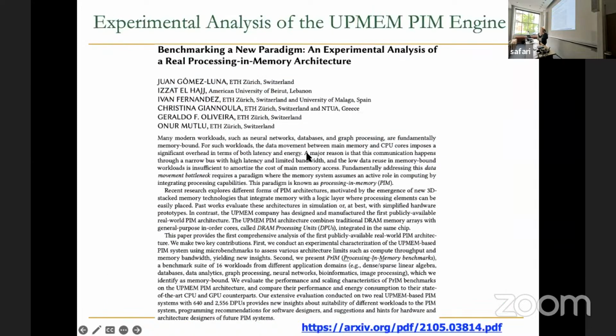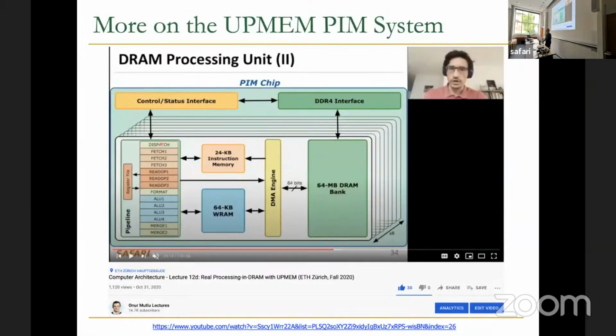There's some shared bus, as we discussed last time, but they're not doing it that way. They're not using that shared bus, unfortunately. They're doing computation, and they needed to modify some mechanisms, but they were not able to touch that part, the DRAM core, if you will. So if you change memory to do computation, maybe you should also think about changing the interconnect on the memory side. But that's not what's done. Even then, I think there are a lot of workloads that benefit.